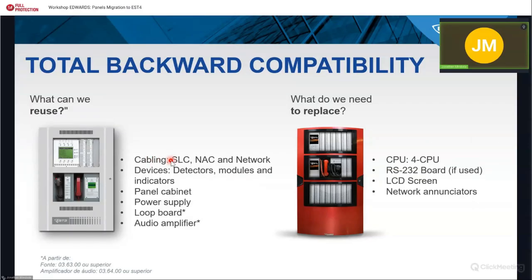The second scenario is when you find an EST3 with audio evacuation and fire telephone. When you see this type of EST3, you must change your cabinet. So you have to change the CPU, you have to change your LCD touch screen, and you must change your cabinet. Why? Because the EST4 structure is different from the EST3.